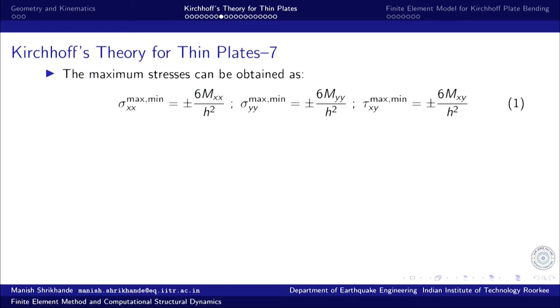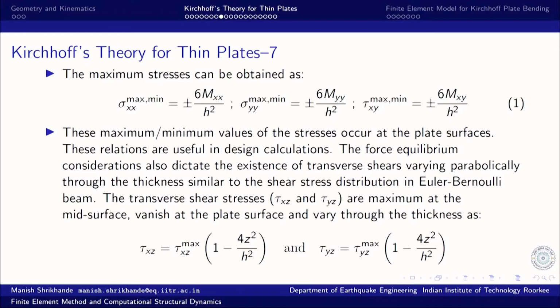So, maximum stresses can be obtained by evaluating these at values of z equal to plus or minus h by 2, and they can be related to the moments. Maximum and minimum values of stresses occur at the plate surfaces, and these relations are of course useful for design calculations. Once we have the moment, then we can simply find out the maximum stress, the direct stresses and shear stresses.